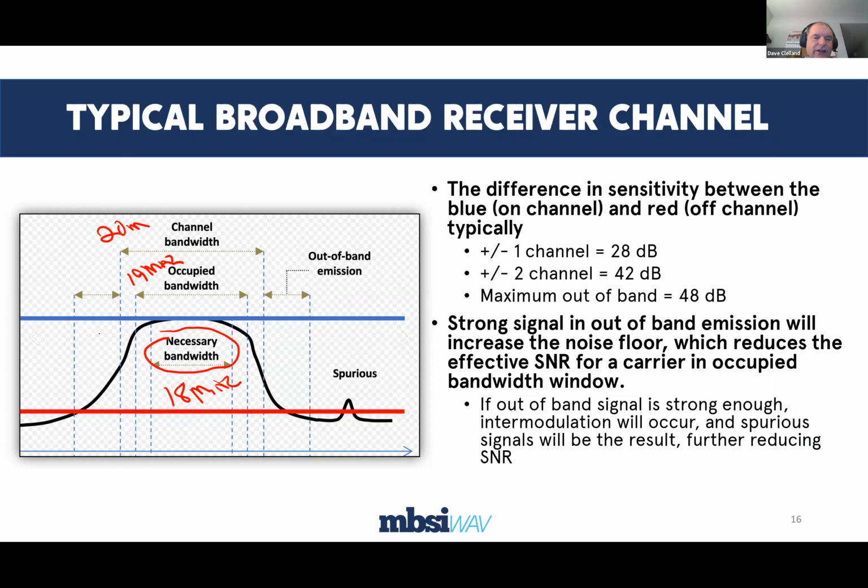And what's the definition of occupied bandwidth? The definition of occupied bandwidth is when the transmitter rolls off a certain amount of power. So the curve, the transmitters are never straight sided skirts. There's always roll off here. There's always energy that's bleeding outside of the channel in every case of every transmitter. No transmitter is absolutely perfect. We could never afford the filters that we'd need to be able to make it perfect. Transmitters would be hundreds of thousands of dollars if we had perfect skirts on them. So we don't do that.